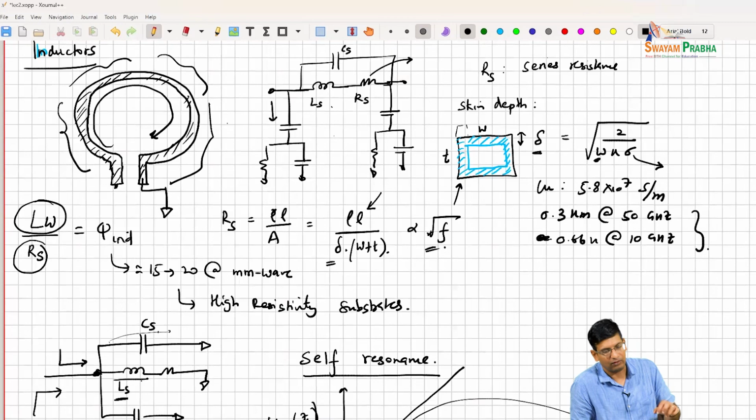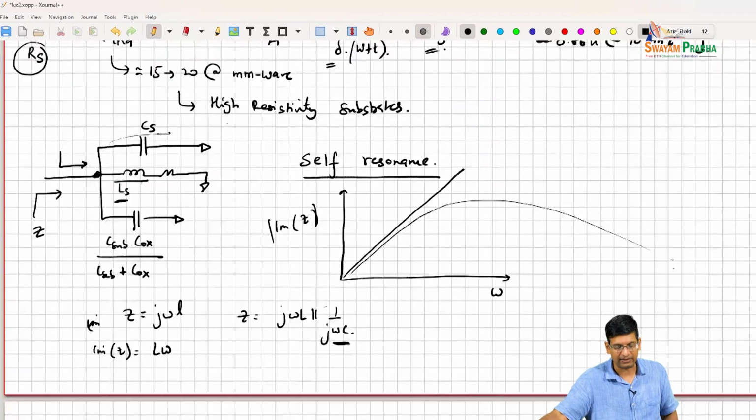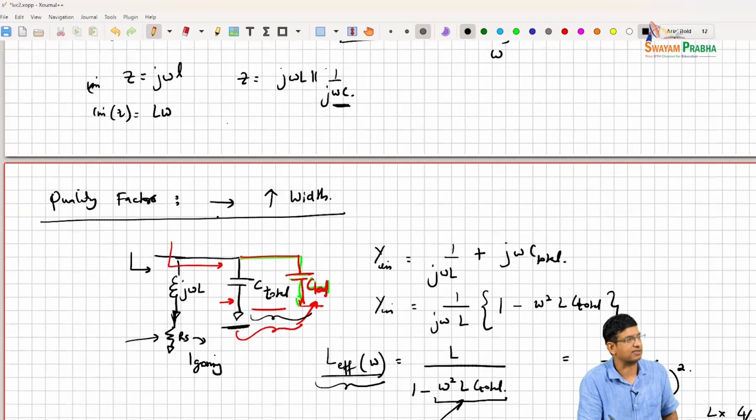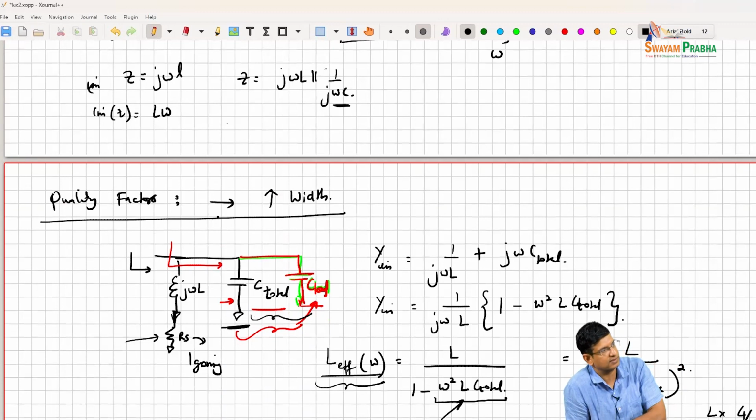And once I have that model, I then try to see if I can absorb the parasitics inside this. At millimeter wave, you are usually counting on absorbing parasitics, because if each component is designed standalone, that's an inefficient way to design the system. Does that answer your question?